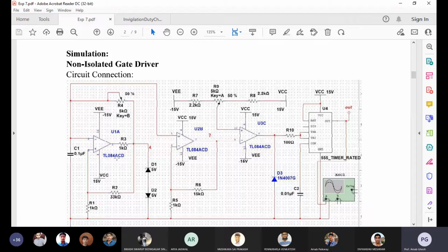So what are we doing? We are isolating. Initially we use magnetic isolation through a LEM sensor or transducer, and after coming back from the DAC, the digital to analog converter, we use an opto isolator.